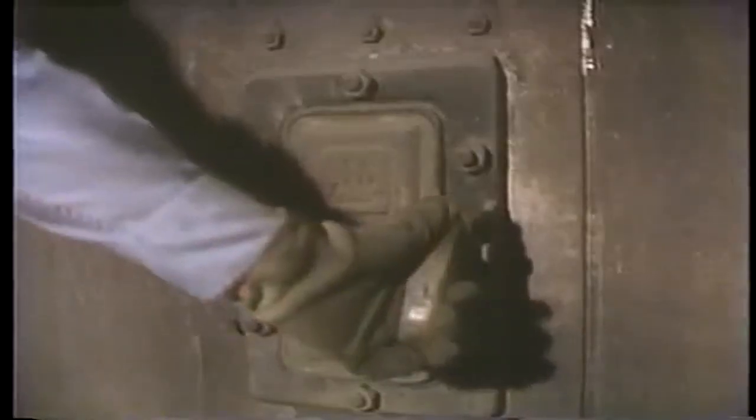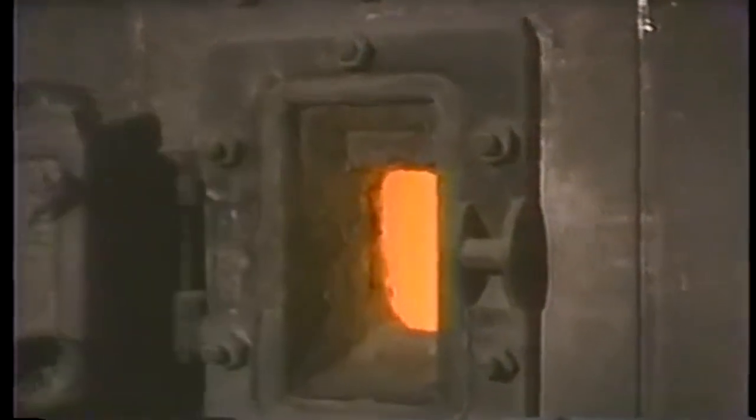They are leaks that occur inside the boiler, leaks that occur outside the boiler, and leaks that occur through the boiler casing. As you know, the inside of a boiler consists primarily of tubes. Water and steam flow through these tubes under high temperature and pressure. Every so often, the temperature and pressure takes its toll and causes a leak inside the boiler. For our purposes, we're going to divide leaks that occur inside the boiler into two categories, tube leaks and tube ruptures. The difference between the two is the quantity of water or steam released inside the boiler and the severity of the problems they cause.